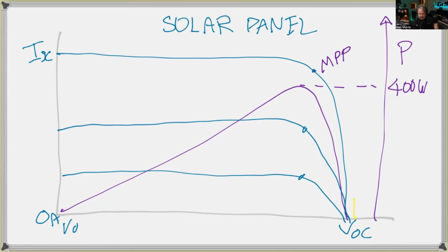So it's drawing, it's a terrible color. Hang on, choose a better color. Tries to draw a small amount of current from the solar panel. And as it draws current, the voltage starts to drop. So it's drawing current, the voltage is dropping. And as it draws more current, the voltage drops more. And so it does a sum. It goes volts times amps equal power. Did I get more? Yes, keep going. So it's technically called perturb and observe. That means change something and see what happens. Really simple. It's just like getting a dial and just changing stuff.